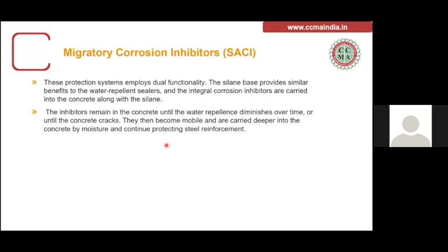The inhibitors remain in the concrete until the water repellence diminishes over time, or until the concrete cracks. Now when the concrete cracks, say after 2 years, they again become mobile and are carried deeper into the concrete, and they continue to protect the steel reinforcement because of the passive layer that is formed around the reinforcement also.